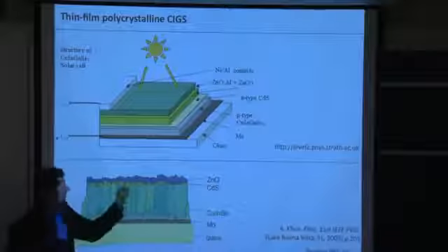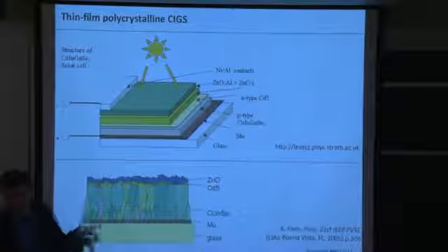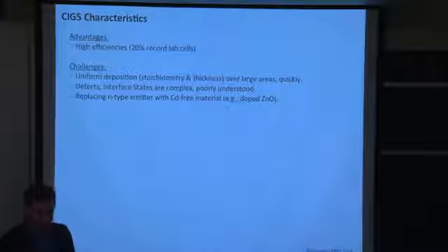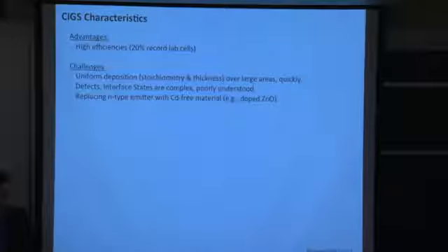There are some minor issues, shall we say, associated with cadmium. There are attempts to go to an all zinc oxide, or maybe a graded zinc oxysulfide buffer and window layer here in the front to get rid of the cadmium. We'll discuss that shortly. And I would say that's probably the biggest near-term challenge. With the removal of cadmium, you can access more markets.